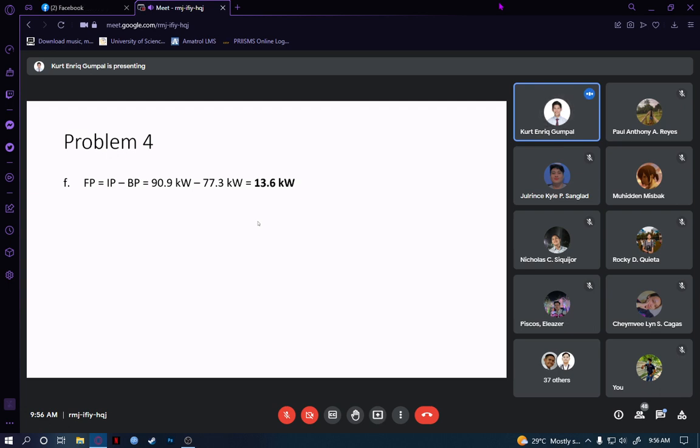Okay? Your G, now. Again, what is your G? Your G is your brake work per unit mass of gas in the cylinder. Okay? So for you to be able to get that, you need to get the heat first per cylinder. So that is 859 kilopascals, your BMEP, multiplied by your displacement volume.